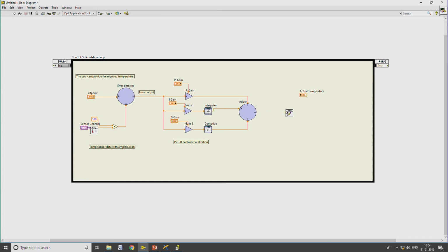So, I have connected this here, but we cannot connect directly. The reason is that since it is a simulation, the system can even provide an infinite amount of data as output, but in reality the data acquisition device cannot provide very high magnitudes. Each device has limitations with respect to operating voltages as well as current. Similarly, even with the USB devices, the output voltage it can generate is 0 to 5 volts. Since the simulation can go beyond 5 volts, both positive and negative, in order not to have any conflict between the values, we can create some kind of a threshold such that if the input voltage is greater than a particular value, send the output as the maximum,